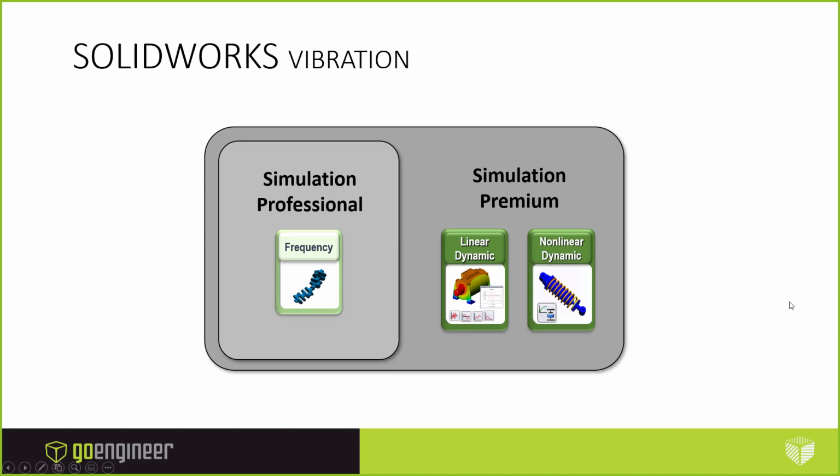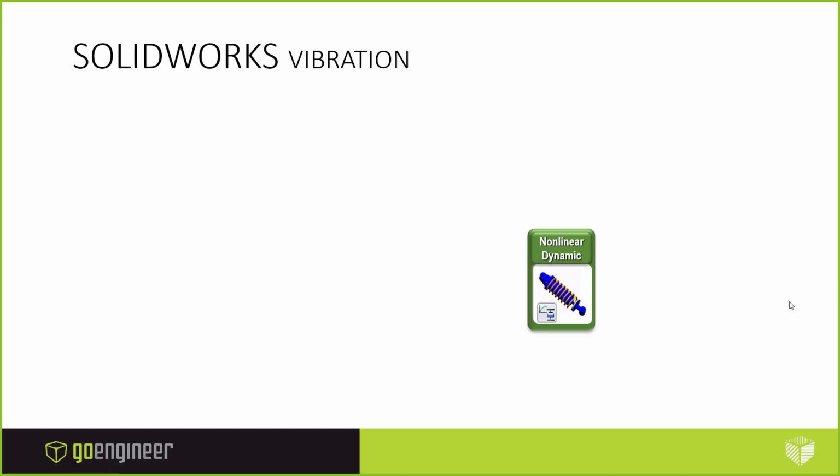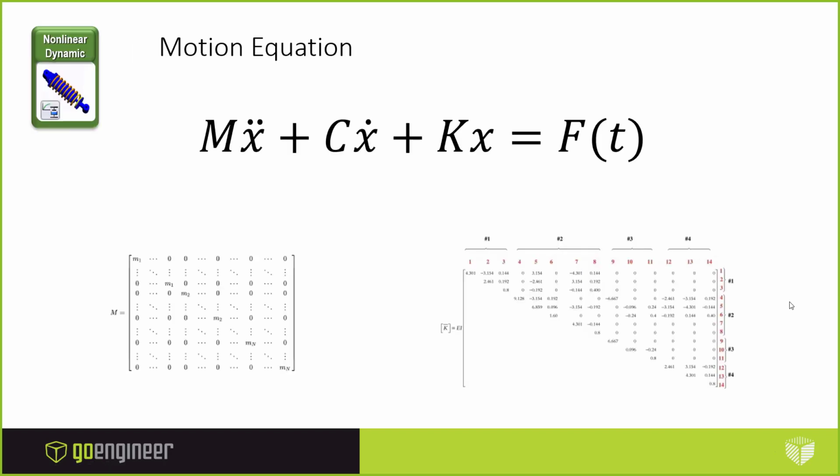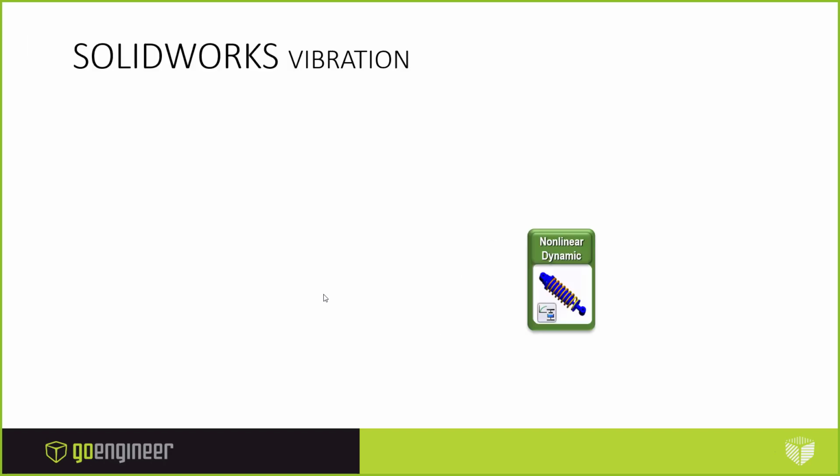Finally, nonlinear dynamic. What's this tool about? Nonlinear dynamic is a little bit more crude, actually. It just solves the motion equation directly. Just does the number crunching. No elegant method here. It's just taking your mass times your accelerations, plus your stiffness times your displacements, and balancing that with any external loads you're applying, and any damping in the system. It's just balancing the motion equation, solving that directly. Okay, so this can take a long time on complex systems, but I'll show an example of this as well later. So it's nonlinear dynamic in a nutshell.